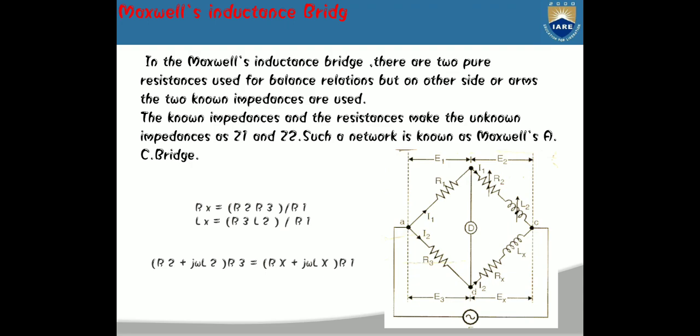There is a minimum magnetization current required to magnetize the core of an inductor. So, the current in the inductor branches of the circuit must exceed the minimum but must not be so great as to saturate the core of either inductor.